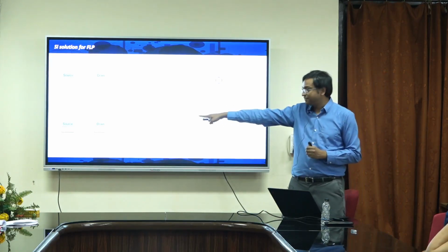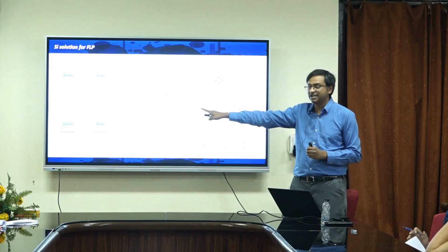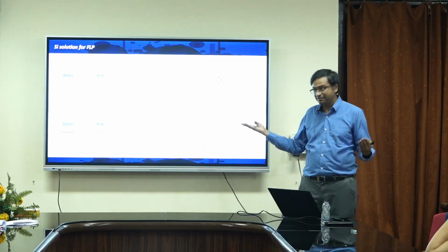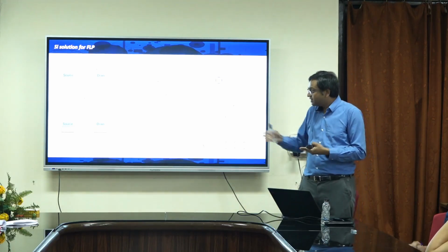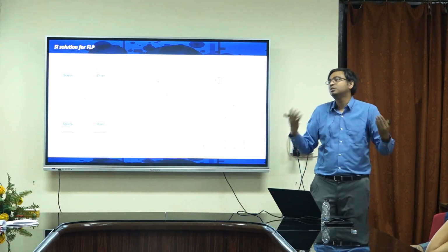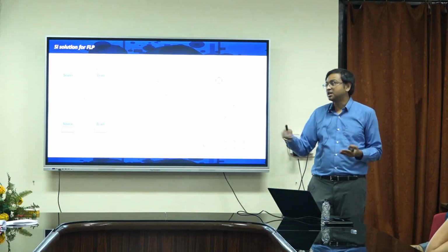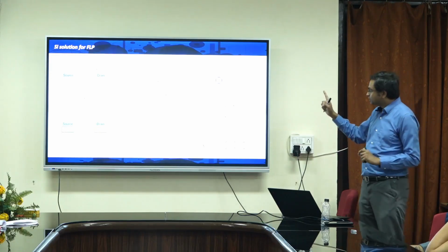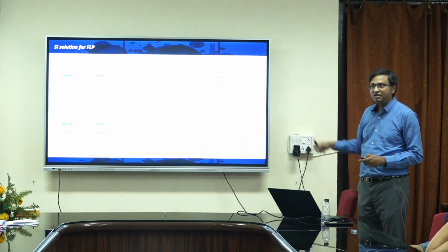This is why in silicon, if you go back and see the actual device structure, underneath the contact they are heavily doped, N++ for an N-type MOSFET, P++ for a P-type MOSFET. Even for silicon we saw that there is Fermi level pinning and a Schottky barrier, but yet in silicon you can make very good contact, because you can degenerately dope it and make the Schottky barrier so thin that in spite of its presence it is almost non-existent. If the Schottky barrier becomes almost close to 0, then the electrons can tunnel through. That is the wonder of quantum mechanics. So, use quantum mechanics to mitigate this contact resistance trouble by degenerately doping the contact.